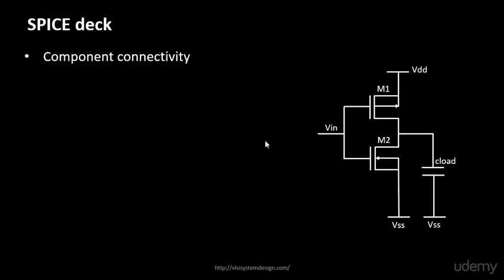Before entering into the spice simulations, the first part is to create this spice deck. Okay, so we have to create this spice deck. Spice deck is nothing but connectivity information about the netlist. So it's basically a netlist that has everything. It has the connectivity information, the inputs that have to be provided to the simulation, and tap points at which we'll take the output and so on. So it has everything. So the first step is to create this spice deck.